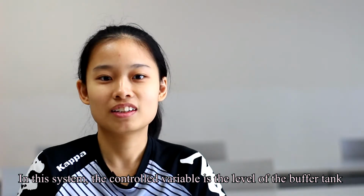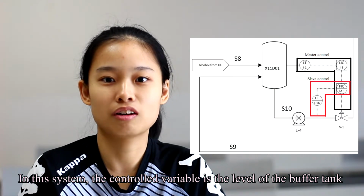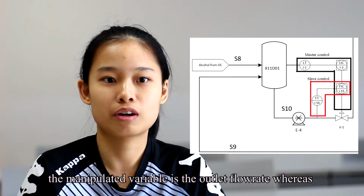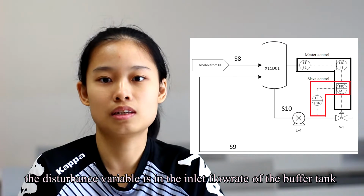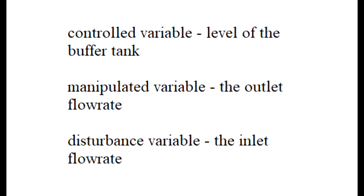In this system, the controlled variable is the level of the buffer tank. The manipulated variable is the outlet flow rate, whereas the disturbance variable is the inlet flow rate of the buffer tank.